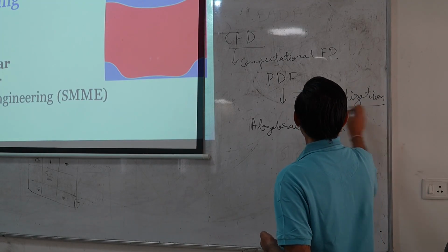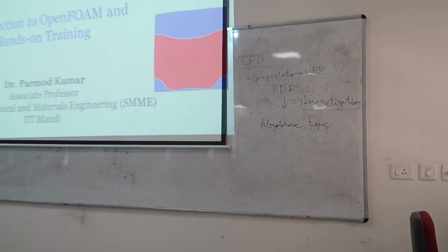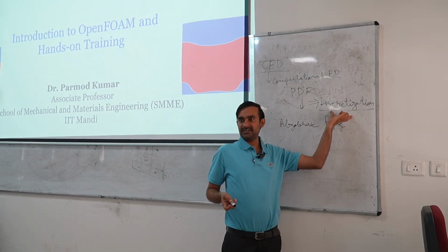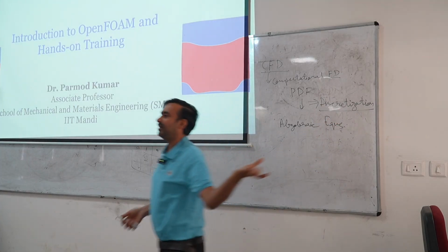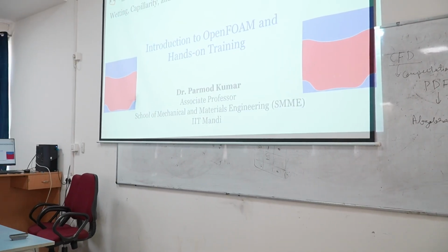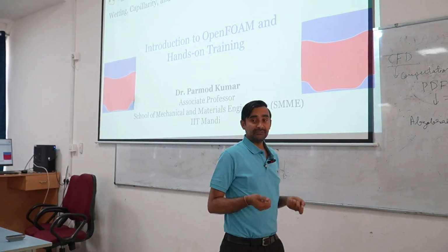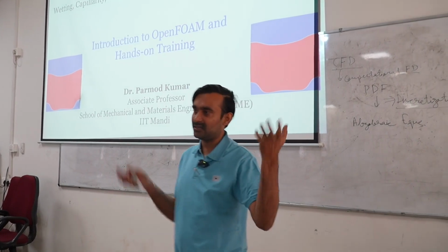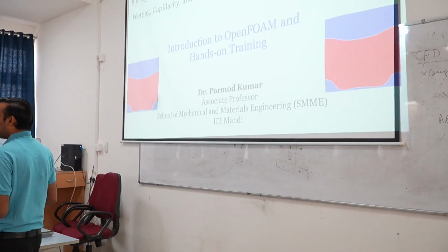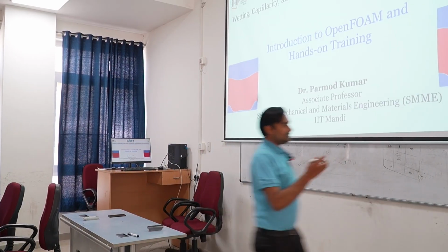Now, when we do discretization, there are different processes. Either I can employ the finite difference method for doing the discretization, I can employ the finite element method, or I can employ the finite volume method. In most fluid flow and heat transfer cases, though other methods can also be used, the popular method implemented in most of the commercial and open source solvers is the finite volume method.